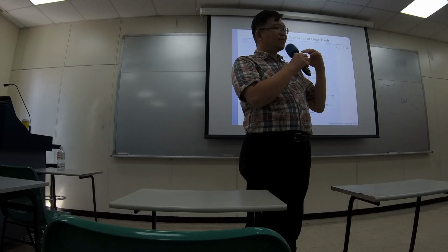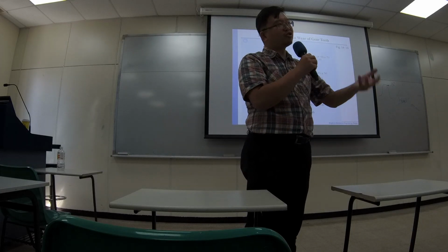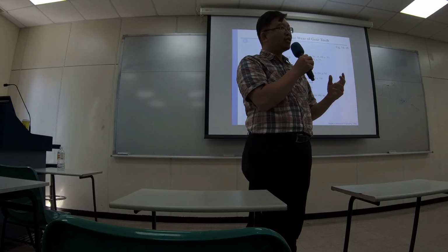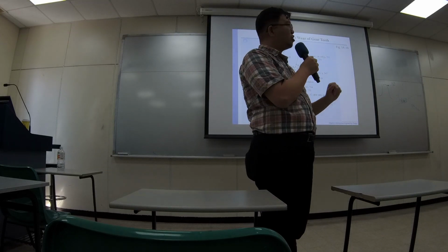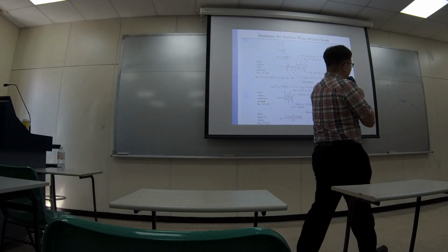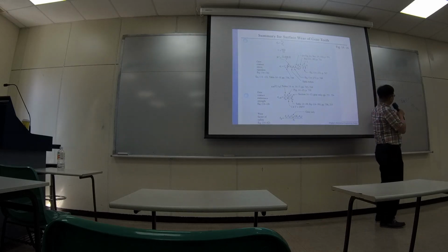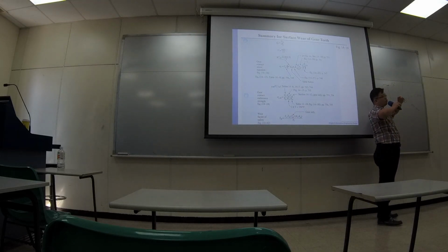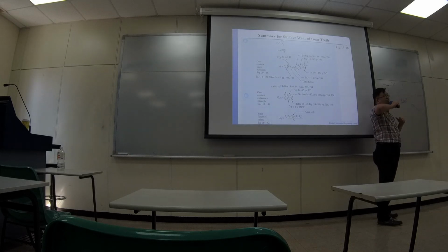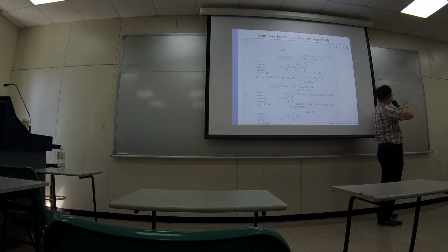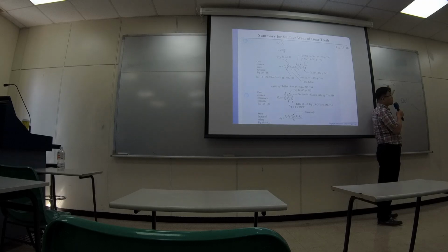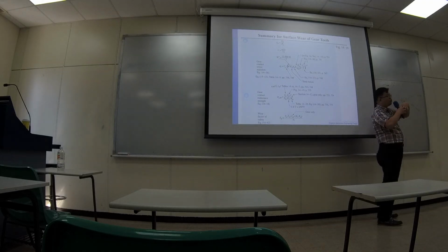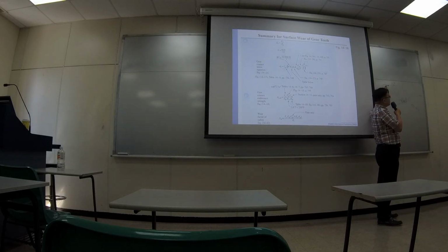So if too much force is applied, it could break. And there are two failure modes. One mode is to directly break the teeth. When the transverse force is too large, you treat it like a cantilever and it breaks directly. And actually, for this kind of conjugate motion, you have highly concentrated forces at the contact area.